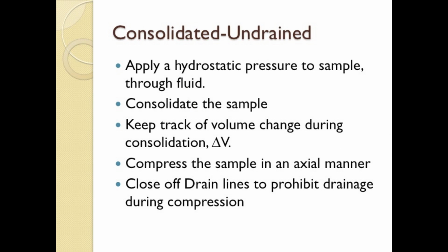A consolidated undrained triaxial test is an axial compression test, but confinement is taken into account. Starting with the test name, consolidated undrained, means the sample is fully saturated and consolidated, and undrained means the sample is not allowed to drain throughout the test.